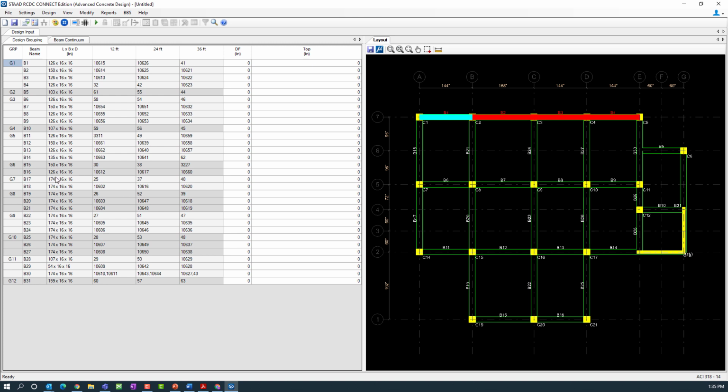It should also be noticed that continuous beams, whether you created your model in the STAAD Pro Analytical Modeler or the STAAD Pro Physical Modeler, will be automatically sent over and grouped together. So here, for example, let's take a look at my imported data. I am hovering on Group 1. The program was able to successfully determine that this was a continuous beam area, which consisted of Beam 1, Beam 2, Beam 3, and Beam 4. It's similar for all the three different levels of your particular structure.